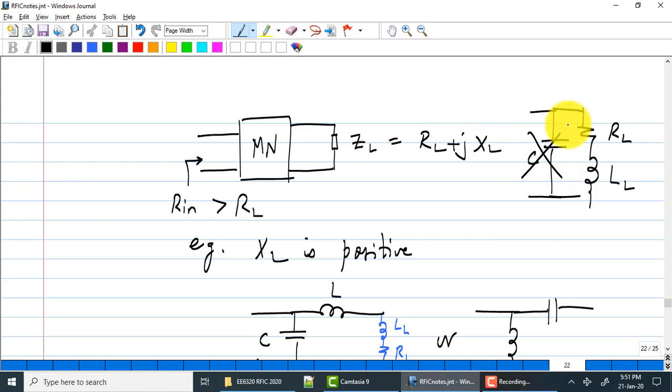Okay. Any other questions? So as you can see, the type of matching network that you choose will also depend on these types of considerations, whether the load is inductive, whether the load is capacitive. And believe me, when you find out that your PA has a capacitive portion also, when you find out that the input impedance of the LNA has a capacitive portion also due to parasitic capacitances, it may be inductive because you may have inductors in the circuit, you will find that these kinds of techniques do come in highly useful. So you have to know these things.